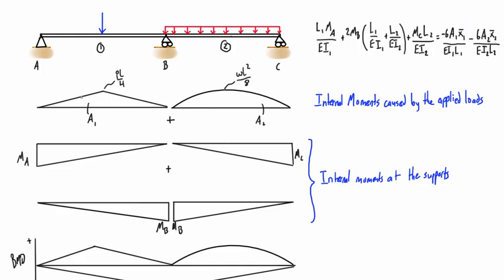And then x bar 1, the centroid of this shape, is the distance from that centroid to the left-hand side. So this would be x bar 1, and then the distance from this centroid over to the right-hand side, basically just going to the outsides that we're looking at for the two-span section, is going to be x bar 2. So you find this area, you find the distance of the centroid. If this shape is not symmetrical side to side, then you might have to do a little bit of composite areas to find the location of that centroid. But basically, you just plug and chug in here.